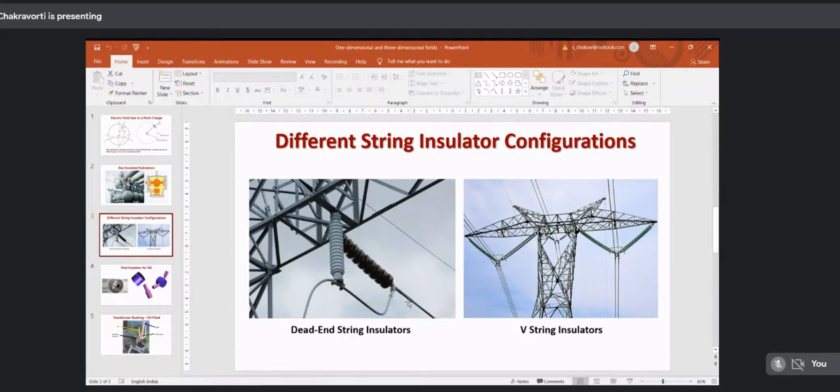So what we do, we take even the single conductor on the left hand side, whatever you are seeing, don't think it is one cylinder. No, never it is that. They are actually multiple cylinders of smaller dimension and they are twisted. They are then called a stranded conductor. So stranded conductor is a different thing and bundle conductor is a completely different thing.